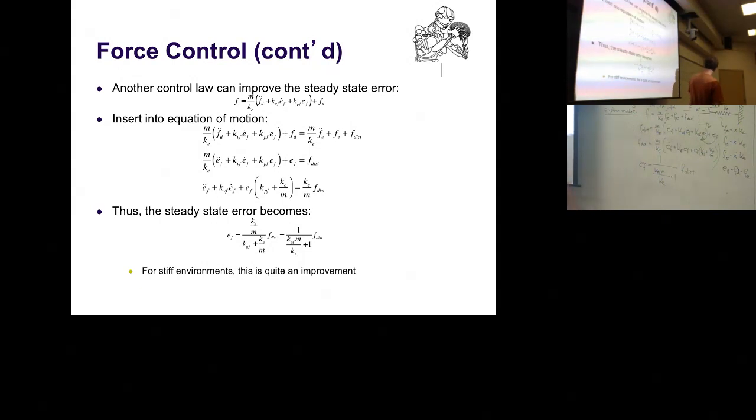Okay? Now, what is nice about this suddenly is now KE is in the denominator here. If KE is really big, which is the case in most problems, then this term here potentially goes towards 0. So we can actually start ignoring it. And we get essentially a remaining error which is proportional to the disturbance force, but not magnifying the disturbance force anymore. Well, it was proportional before, but it's not magnifying it. It's basically something which is smaller usually. Okay. And that's a huge improvement if you want to basically execute that.